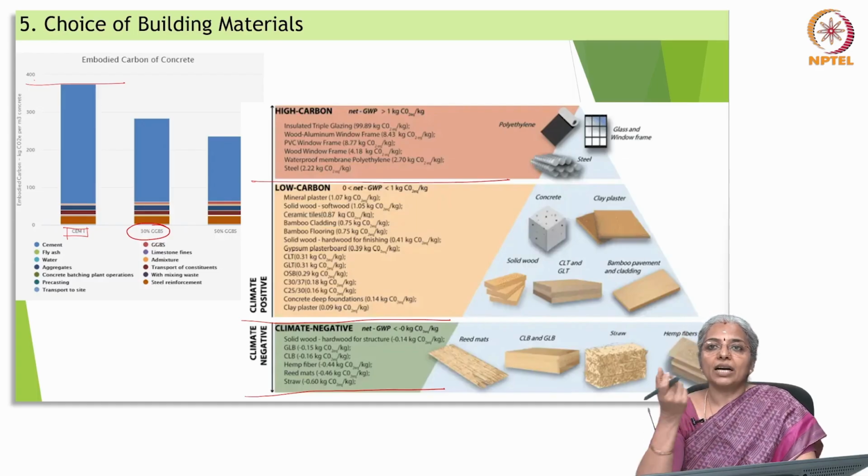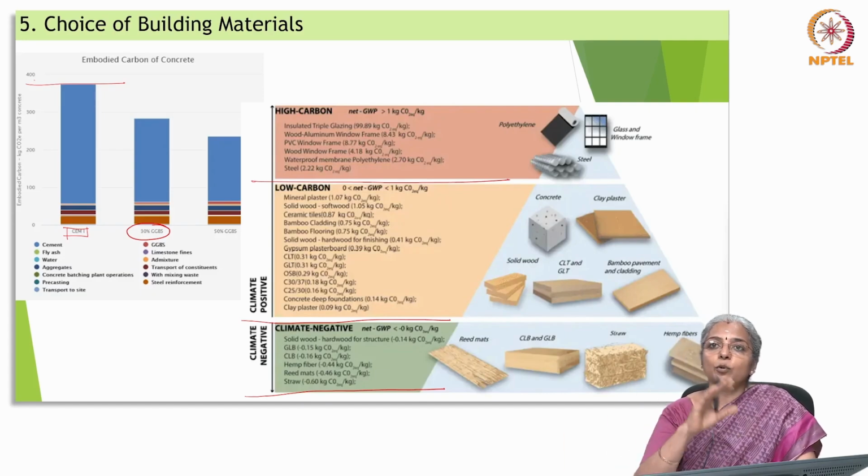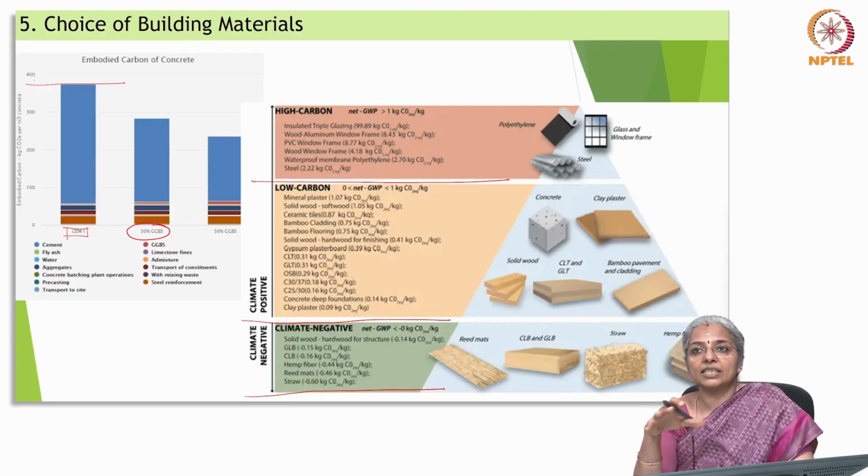Even low embodied carbon finishes represent a small part of the total, but they can have a positive impact when you start adding up the rest of the improvement measures, and they help to further reduce emissions. Considering exposed concrete for floors and ceilings is also a very effective way to reduce finishes and therefore reduce embodied carbon.